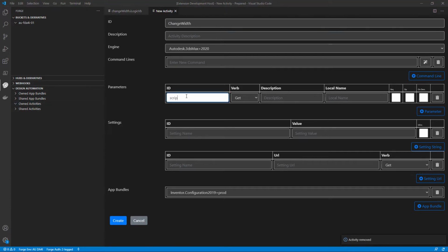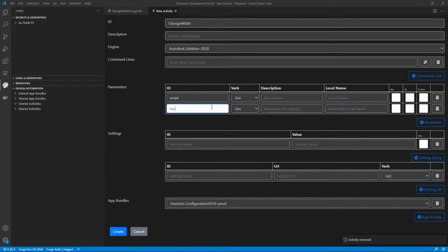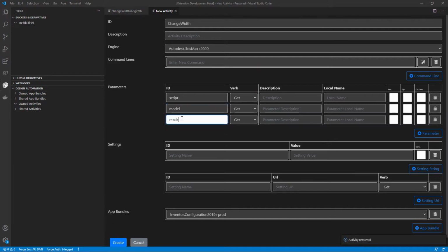First option may be to deliver it as design automation parameter, besides your box part. Make sure your model parameters specify local name with IPT extension. If you will not specify proper extension, Inventor refuses to open your design as unknown, based on your extension.